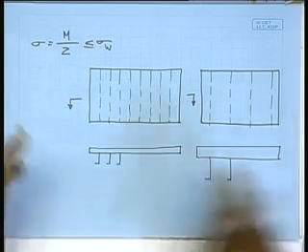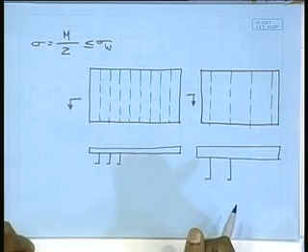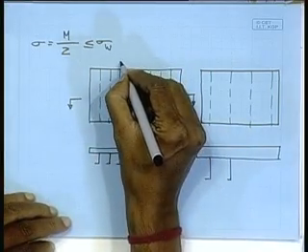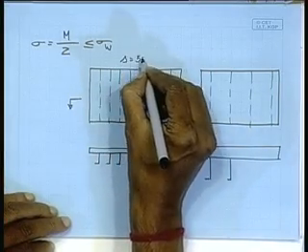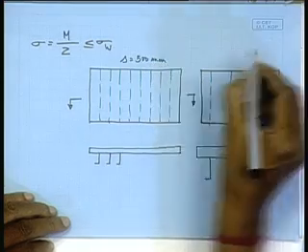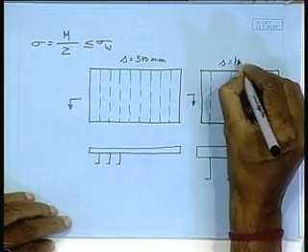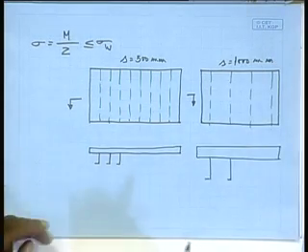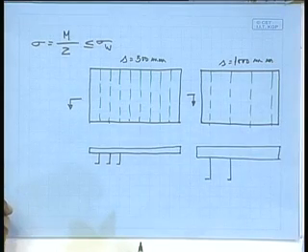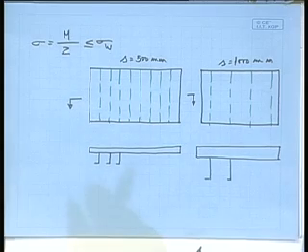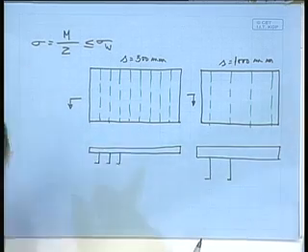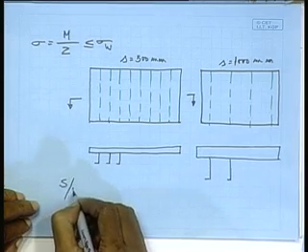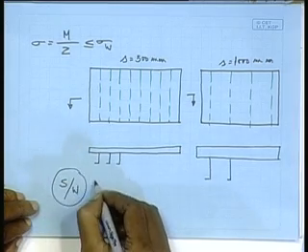So what is the ultimate difference between these two? Which one to choose? Now, tell me. Here I have provided frame spacing 500 millimeter, and here I have provided frame spacing 1000 millimeter. Which one to choose, or choose something else altogether? 500? No, what should be the criteria? There has to be some criteria. Strength by weight ratio. Simple. The criteria should be strength by weight. It has to be maximized.